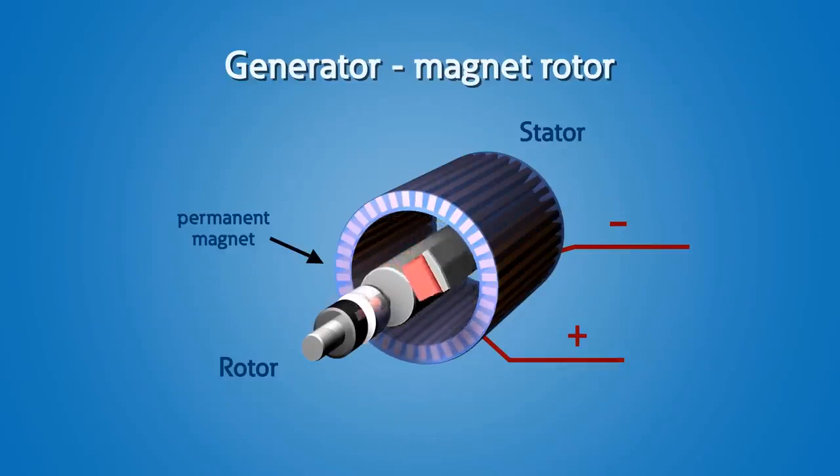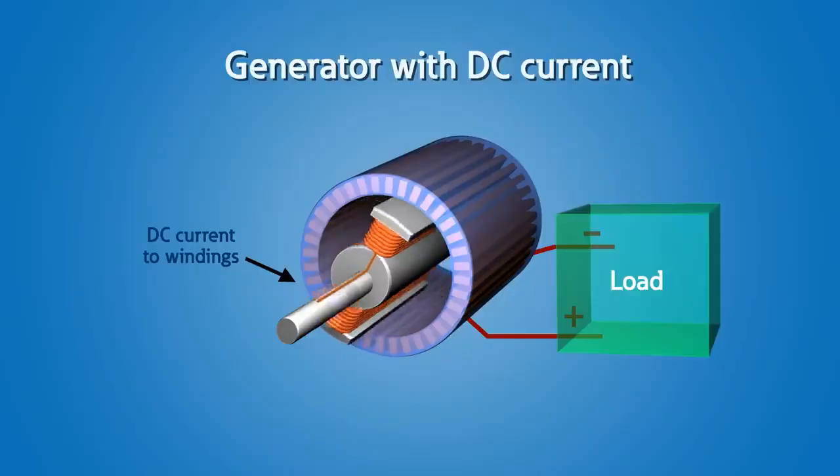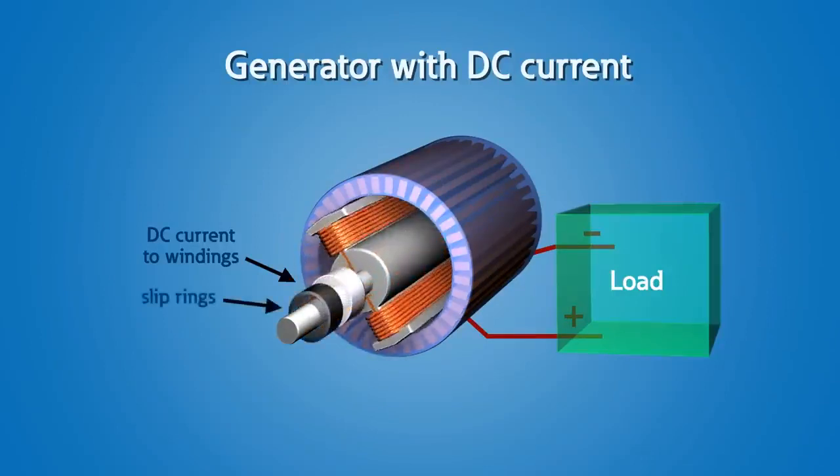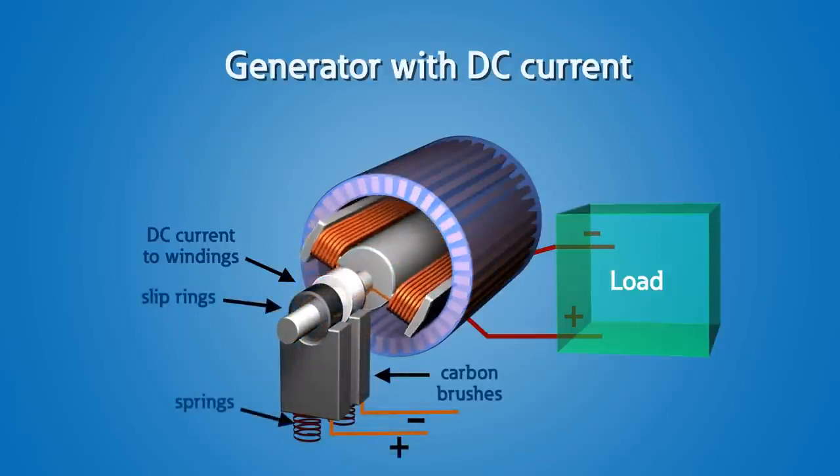For a generator to produce power, an electromagnetic induction must occur between the field windings in the rotor and the armature windings in the stator. A magnetic field must be created in the field windings on the rotor. Traditionally, this was done using permanent magnets, but with larger scale generation being needed, electromagnetic field coils were able to produce substantially more power. This is done by applying a DC current or excitation current to the field windings through a pair of carbon brushes and slip rings.